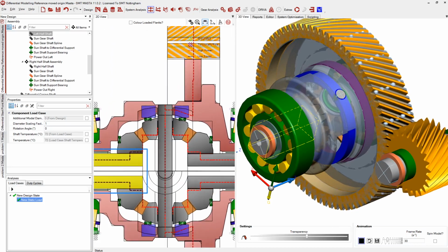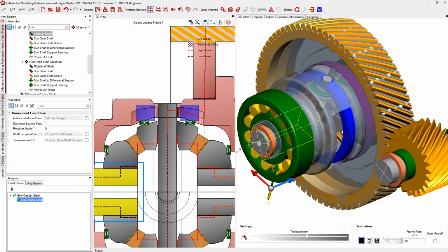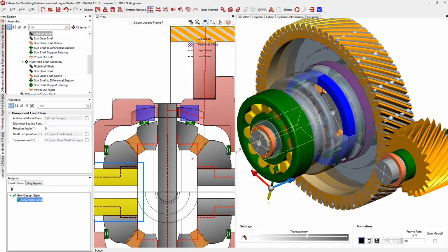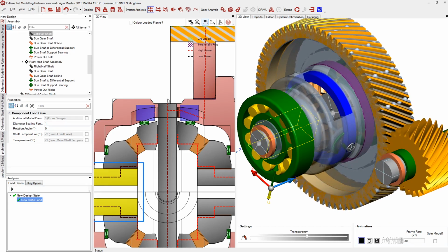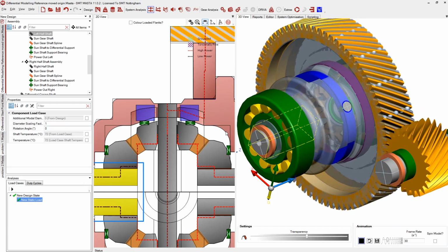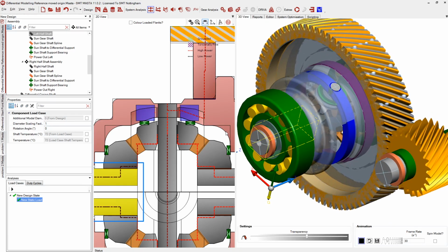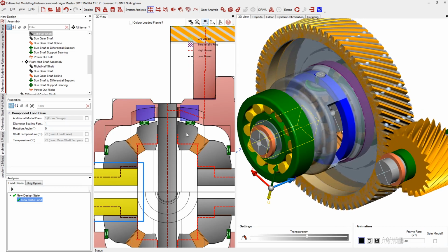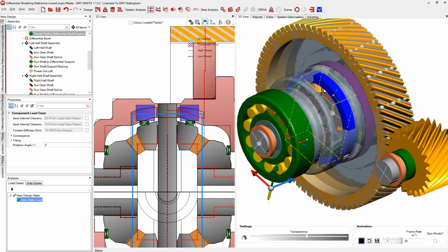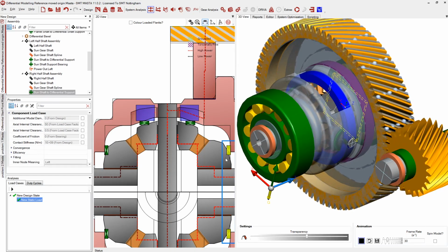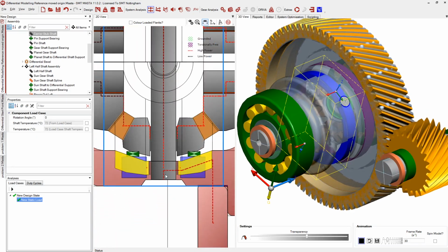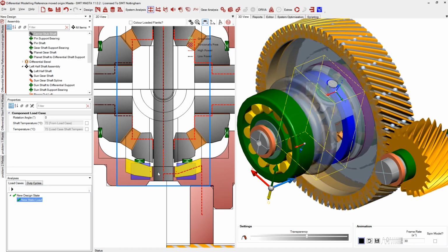Now the reason we need a specific video for this is generally these components around here. There is some confusion as to why exactly we need this configuration and what we do to actually model some of these components. Obviously I'll go through this in more detail as we progress through modeling our own system, but the main ones I want to bring your attention to here are the bearings, which are scattered around the differential model, and this small shaft section highlighted at the bottom, which we're calling our stub shaft.